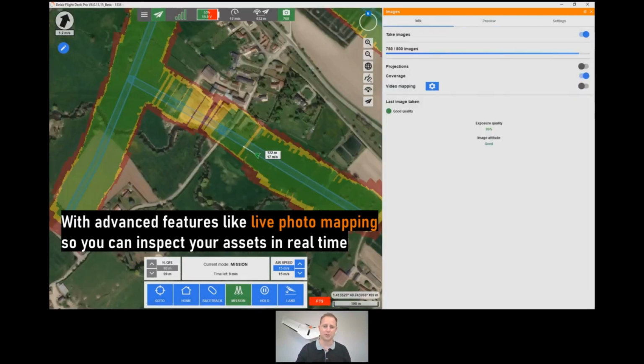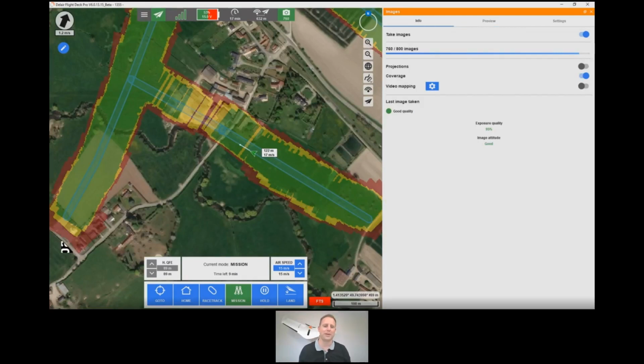The other thing we can do is this overlap map, or this overlap detection. So red, yellow, green. You can tell on that first pass over that power line, as you would expect, there's not quite enough overlap to have it stitched together. So as it goes back over, we're just making sure that any point has at least full overlap with another photograph. Actually, I think we're looking for 4 photographs or something like that. So anywhere it's green, you have excellent overlap.